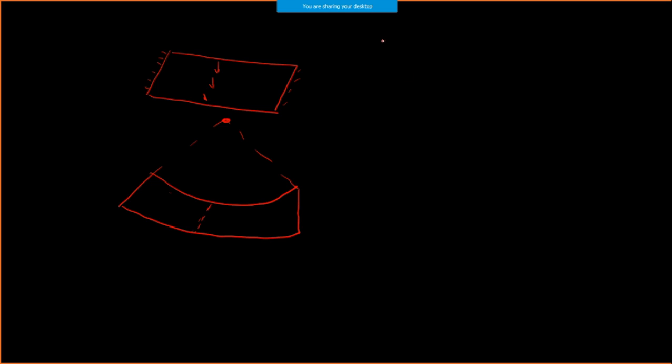Curvature is represented by d2u by dx2 if I'm going to do only a 1D analysis. If I'm going to do a 2D analysis, then it becomes d2u by dy square, and if I'm going to do a 3D analysis, then z also comes. Whenever you do an analysis, my request is that first of all, concentrate on only one direction, and the same is applicable for the other directions in 99% of cases. If you are considering anisotropic or non-isotropic materials, then that will be something different.